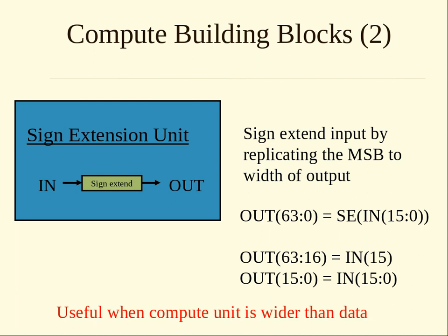Yes? So is it just like 16 to 64, or does it have different effects based on the starting amount of bits that you use? So the trick is, we haven't talked about how you encode positive or negative numbers. That's the problem. I know, chicken and egg, but all the sign extender does is take the most significant bit and copy it over. Hopefully you can see that's a really easy way to do sign extension.